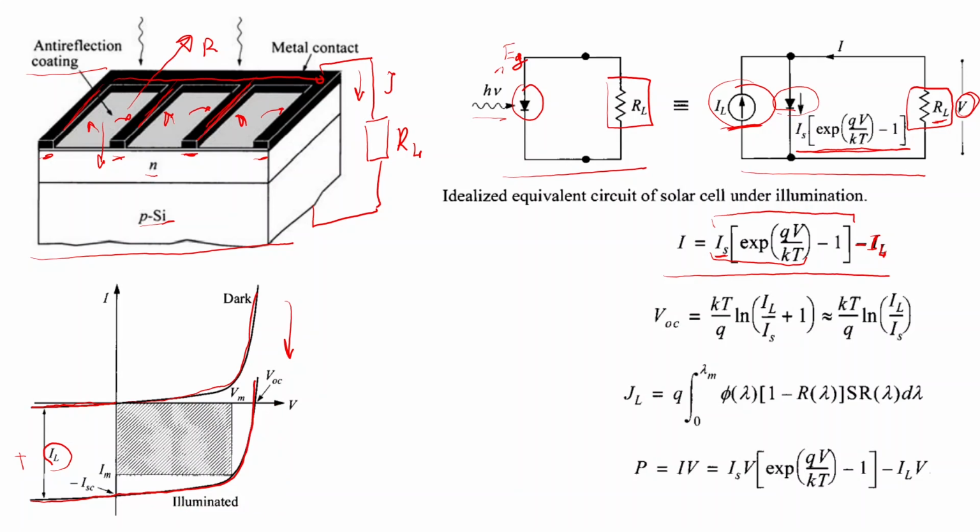Now we come to the photoelectric parameters of a solar cell. Here we have short circuit current, which comes with sign minus because photocurrent is negative, and this short circuit current is also considered as negative. So this is for an ideal solar cell when we don't have series resistance. It coincides with photocurrent, so we can define this as the following integral.